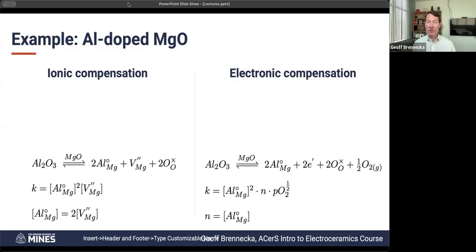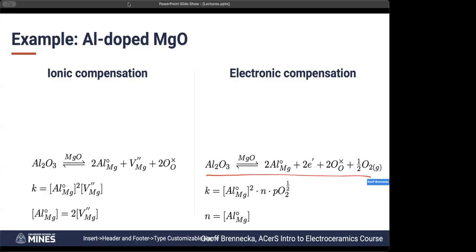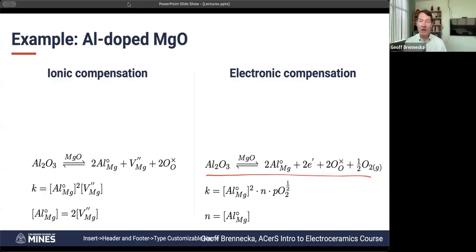But keep in mind, during the sintering process, and we'll talk about this, hopefully we get to it later today, if you've already done calcination, the chemistry is finished, and the sintering portion is just the physical reactions without the chemistry occurring. Whatever chemistry we're representing with these equations is happening whenever that reaction is occurring. But again, we can sort of tweak this during the sintering process, during post-processing, that kind of thing. We'll get to that a bit later on. I want to walk through the equations first, and then hopefully you'll see why they matter as we get along.